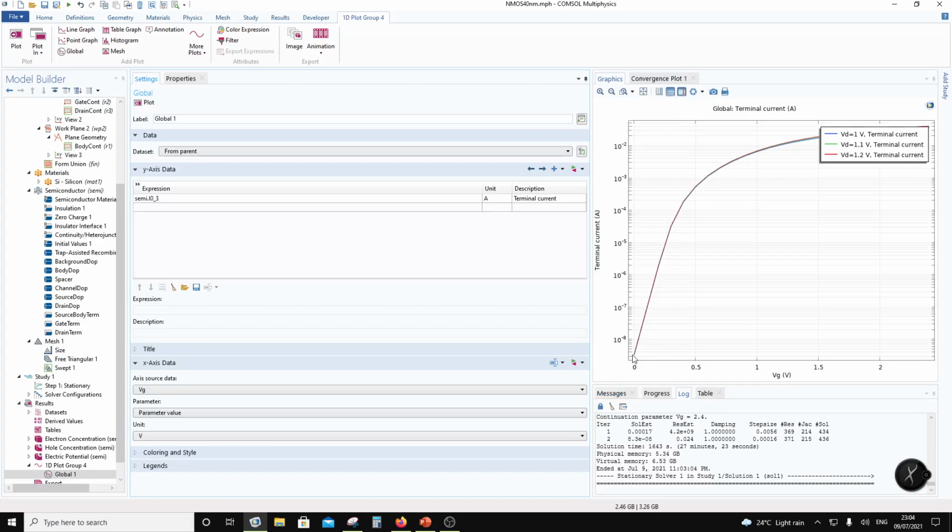You see that you have around 10 raised to minus 9, okay, is the subthreshold current. And then if you find out the slope in voltage per decade of the current, that will be called the subthreshold slope, right? And then over here you can see somewhere where this linear ends, that would be your threshold voltage.